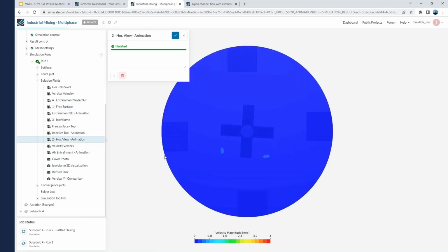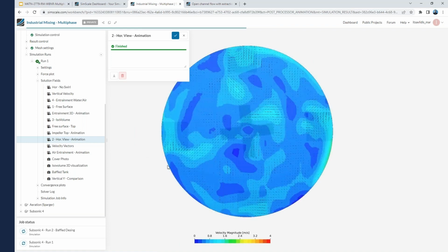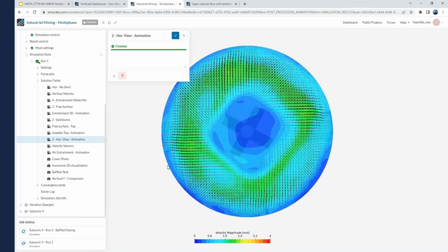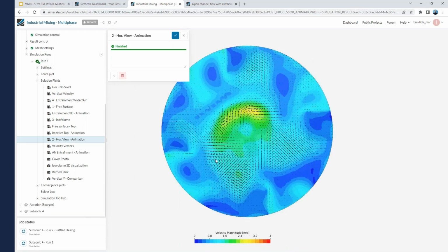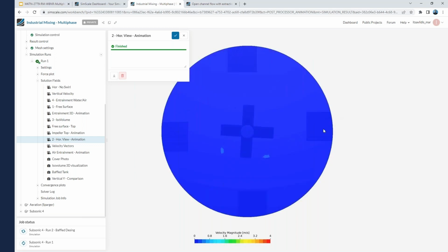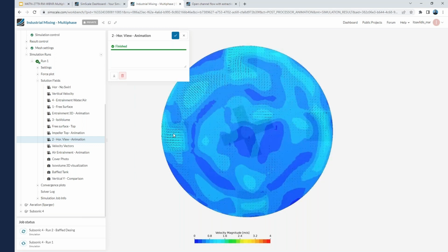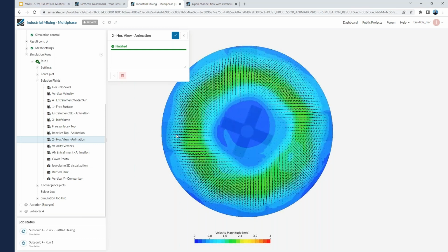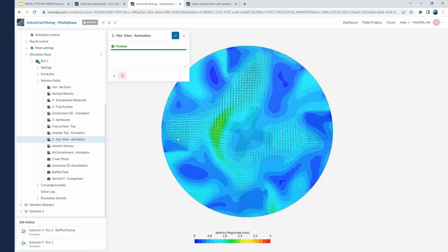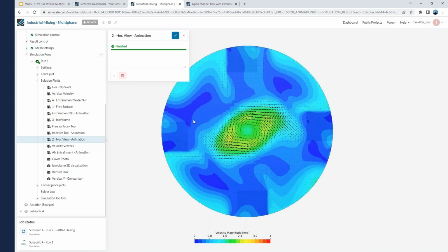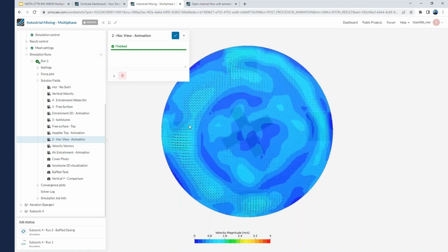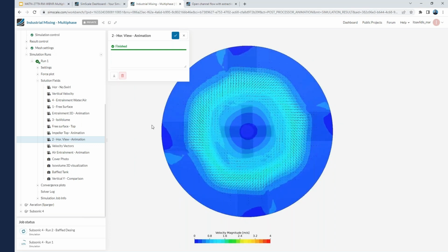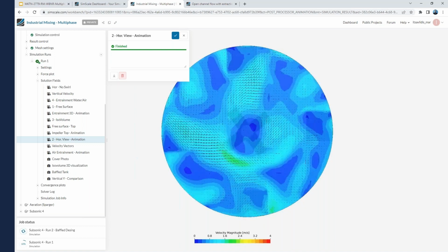In terms of the horizontal view flow, you can see I no longer have a strong rotational flow, a strong swirling flow. Instead, I do get a more randomized flow. Here are the baffles, you can see them in the background. At baffles level, I only get some random flow behavior. It's definitely not rotational, but it's probably top to bottom, down to the top behavior. So that's good. It promotes my mixing.